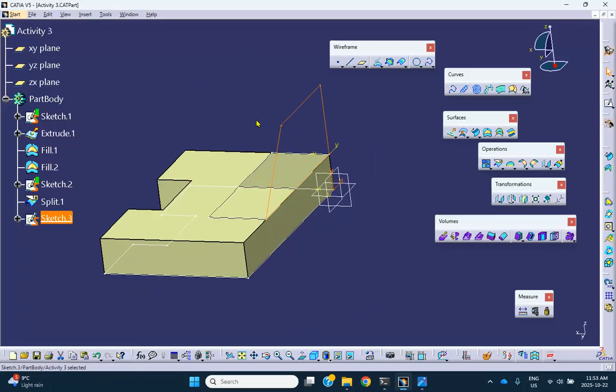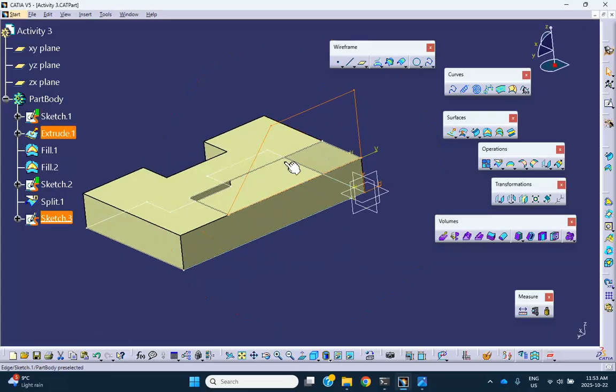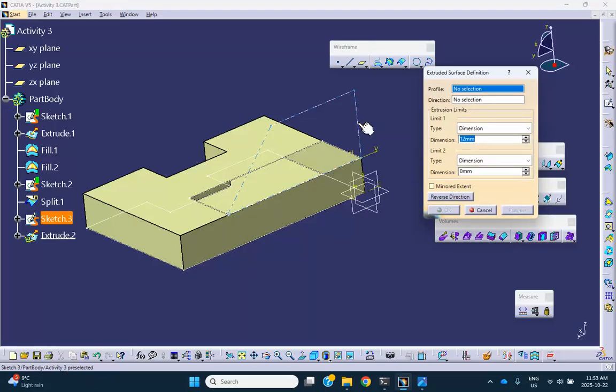I'm going to extrude this thing by 20 millimeters. The only thing is that when I extrude this by 20 millimeters, it also creates a bottom surface here. So maybe it's easier if I did an individual line extrude. The only problem is that when you try to extrude this, the whole thing is going to get extruded.